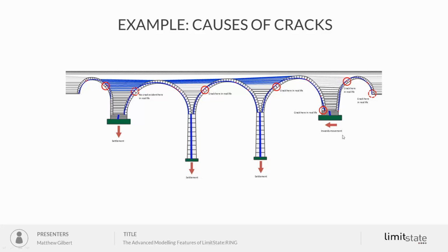And the other interesting thing in this bridge was looking at the capacity of the bridge with quite severe distortion, particularly of the right-hand span. And in this particular case, we found that the consequences of the distortion on capacity were not that great. So I think it's something you have to look at on a case-by-case basis. Sometimes quite severe distortion can be less damaging than you might think.